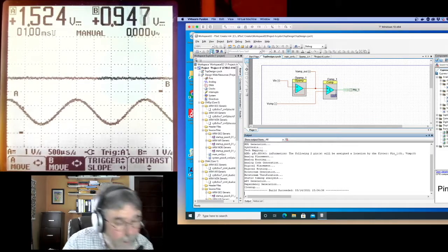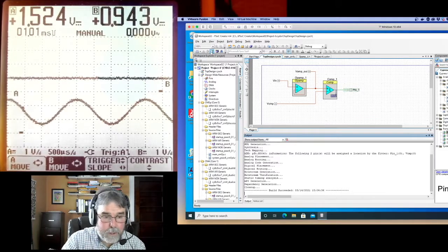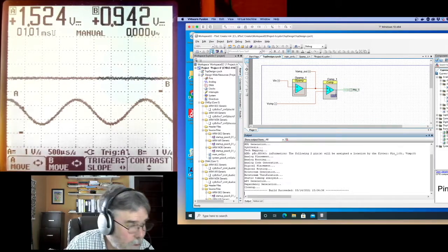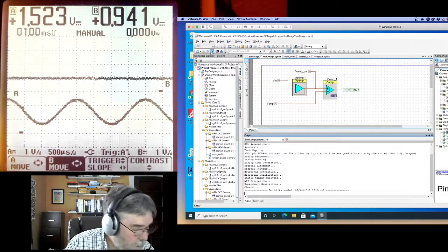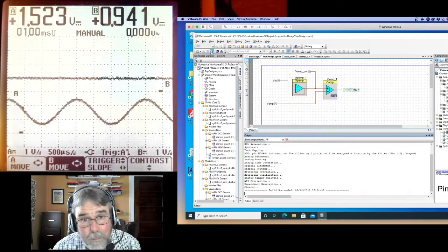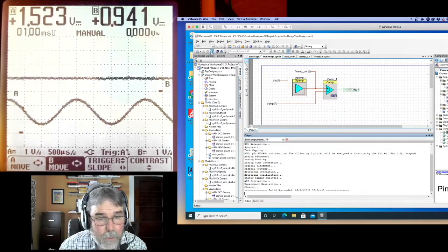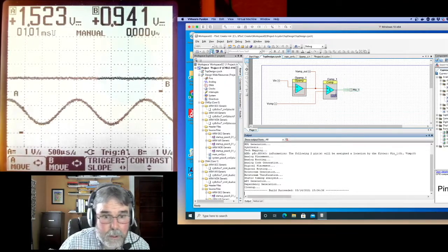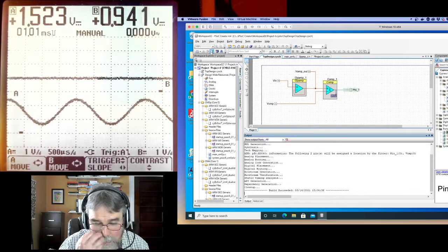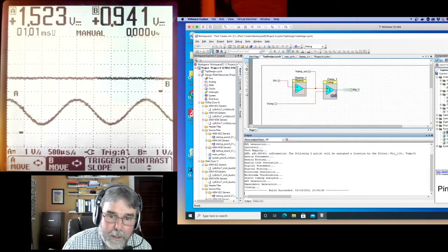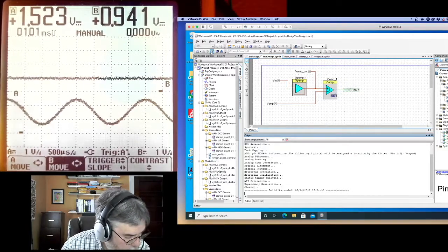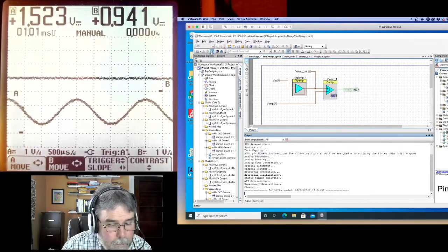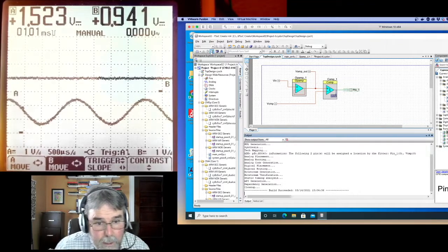I can make it 0.5 volt just by adjusting that potentiometer. But of course, if you had a couple of fixed resistors, you could still get a divider and get pretty much any voltage you want. I can bring some potentiometers to the lab on Thursday if anybody wants to try using one of those. And of course, you can also just use the bench DC supply. You just connect ground and the output of that DC supply, and then you can adjust it to whatever voltage you want. Okay, it looks like that built okay.